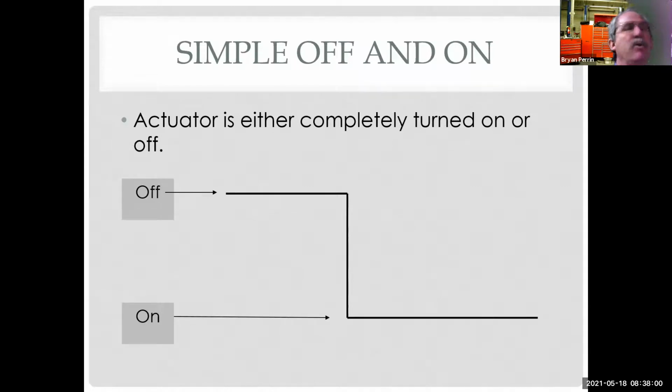Even as we move into these more advanced controls, this principle of voltage off and ground on is consistent throughout all 4 ways of control, because everything I'm going to show you is a ground side controlled circuit, because overwhelmingly that's how we do it, probably 90% of the time. It is overwhelmingly the most popular way to do it. If it's high side controlled, everything's flipped.